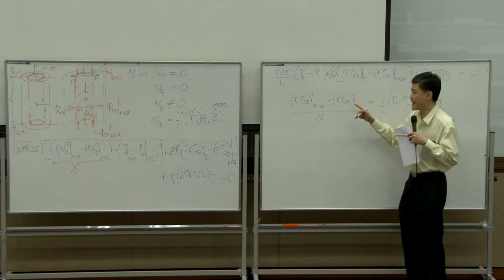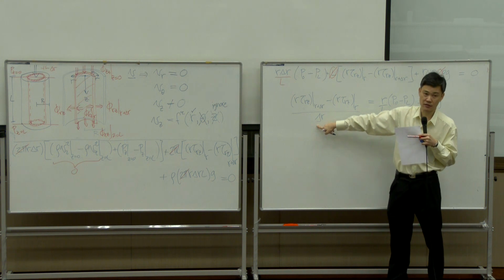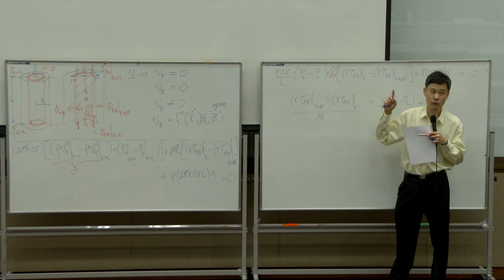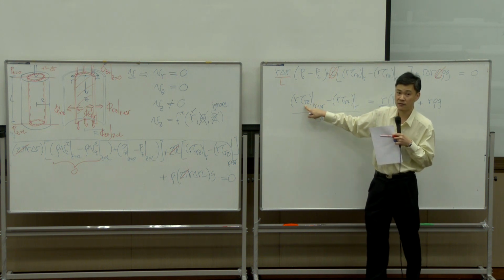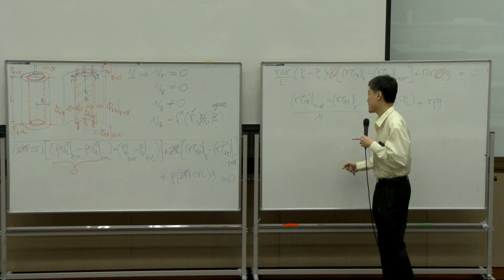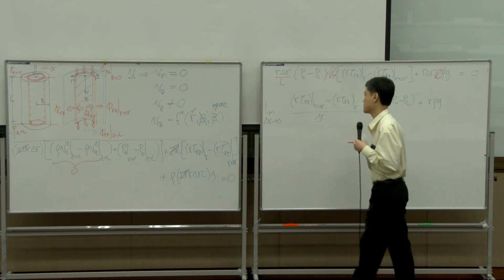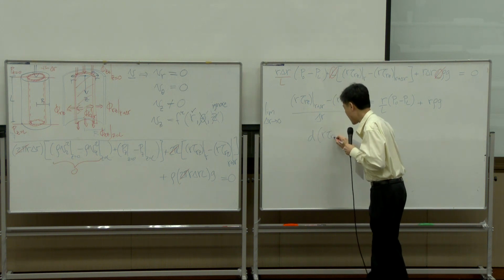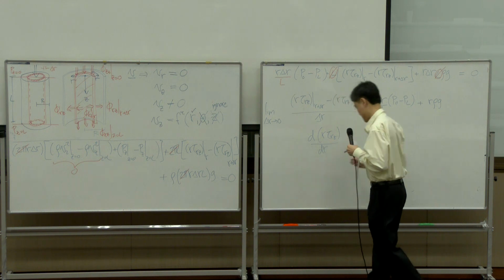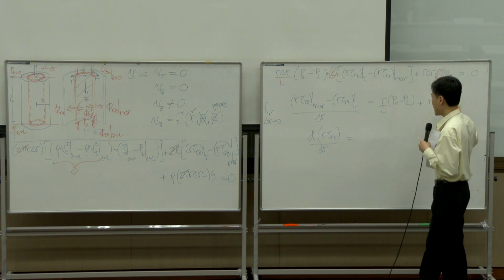So you see that unless you work on this, you cannot come up with this structure. And that will be a mess. So whenever you work with cylindrical coordinates, please remember to bring R and tau together. So if you take the limit delta R approaching 0, then this term turns to be the differentiation of R tau Rz with respect to R. Right hand side remains the same.